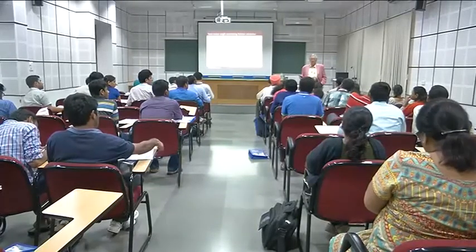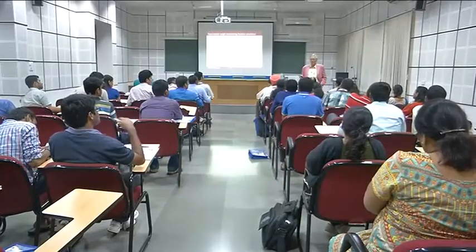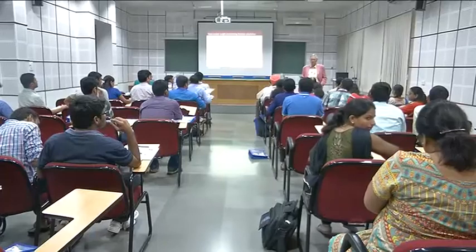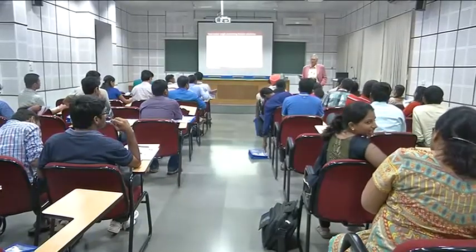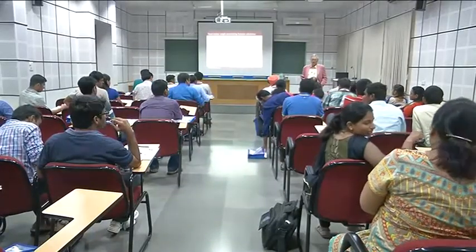Well, the original turbo code had memory 4. It was a rate 1/2 systematic feedback encoder with memory 4. So that would be 16 states. In the standards, they've used 8 states, I think.